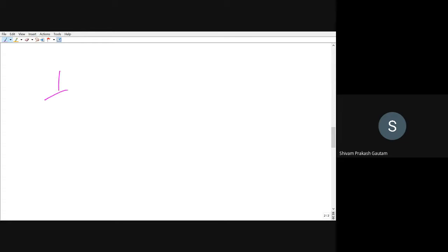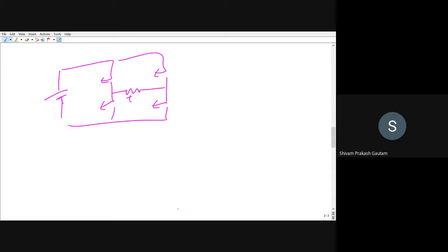So if you go with a basic level, not 5 level, just a 3 level, you can see there is a load. Let us suppose plus minus. This is VDC. You can number the switches 1, 2, 3 and 4, and connect an anti-parallel diode to each, because this anti-parallel diode is already embedded in the switches. Generally in multi-level inverters, we will use IGBT as our switches, that is insulated gate bipolar transistor. This we will use because these are basically useful at medium power.